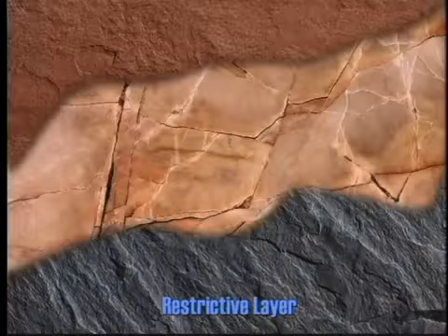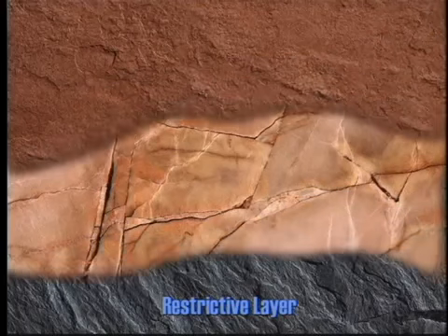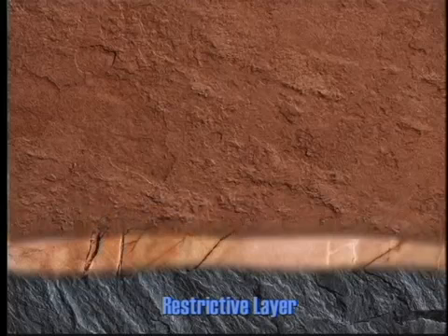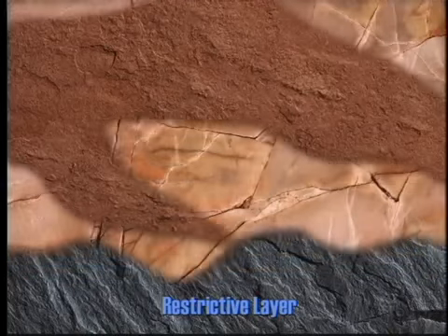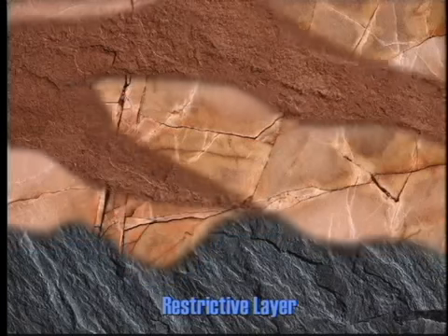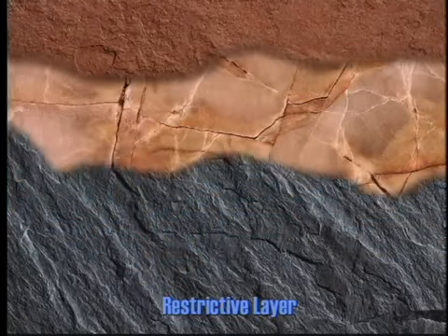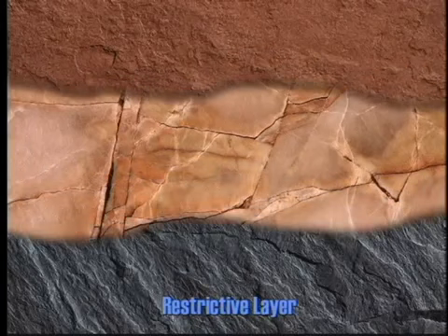The evaluation of soil in the treatment area should reveal the most restrictive layer in the soil. This layer will determine the quantity of water that can flow through the system, as it limits the flow of water through the soil. To find this layer, you evaluate the soil below the bottom of the land application system. Presence of shallow groundwater will limit the ability of the site to treat the wastewater.